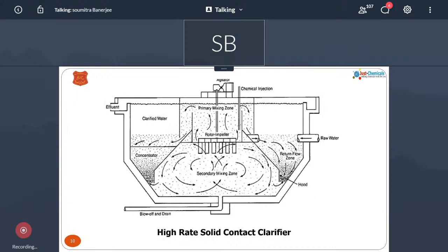Yeah, this is the advancement, where there are two biggest differences between the conventional clarifier and these clarifiers. One is that the detention time required has now reduced to 2 to 2.5 hours. That means half the time is required, half the area is required, and half the capital cost is required compared to those conventional clarifiers. Second, the chemical dosing and chemical requirement are also lessened because this takes up the already formed sludge and tries to mix it with the sludge.